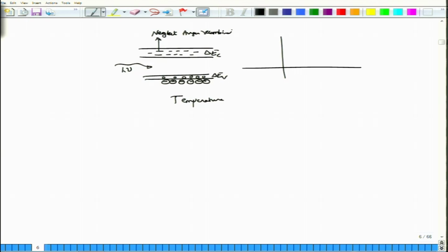So this is the first thing that could have happened. What we are now seeing is that the light which is now incident can stimulate electron to hole recombination, right, thereby increasing the amount of photons that are available at appropriate energy levels. Now this is very important, at appropriate energy levels, because this energy may be equal to this transition, or it could equal this transition, right. So you need to have an energy which is greater than Eg, of course, but within delta Ec and delta Ev plus Eg, right.